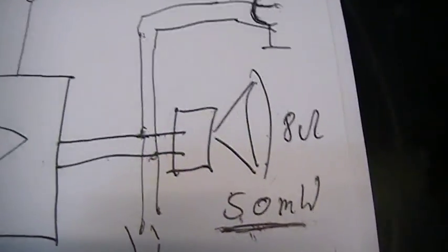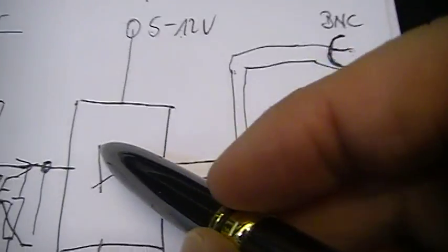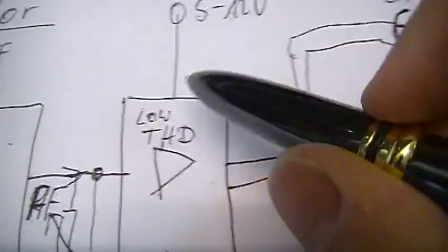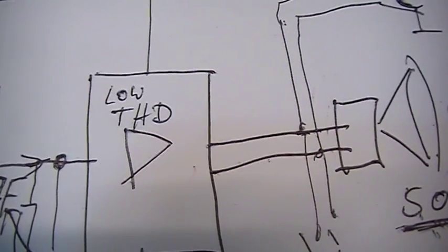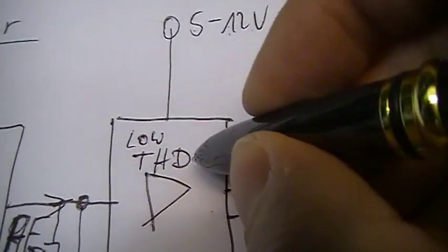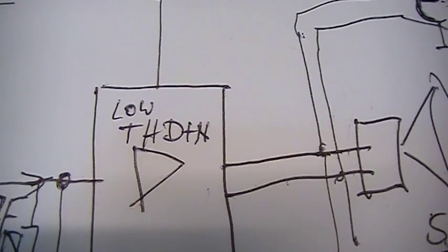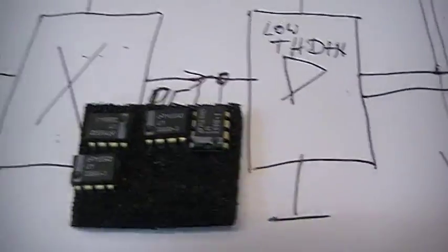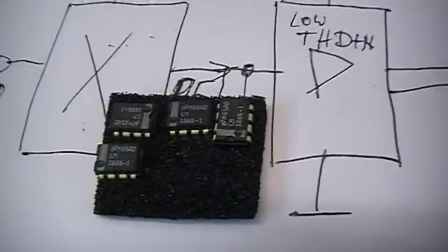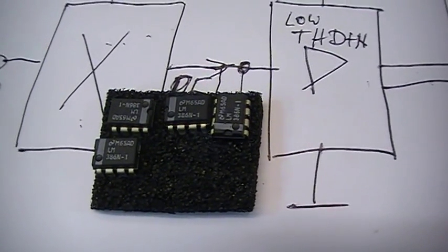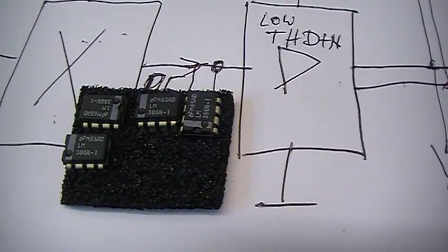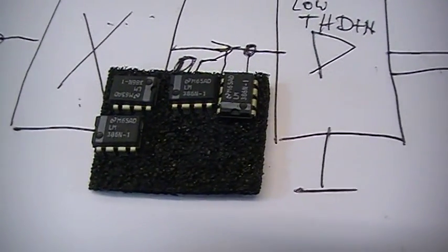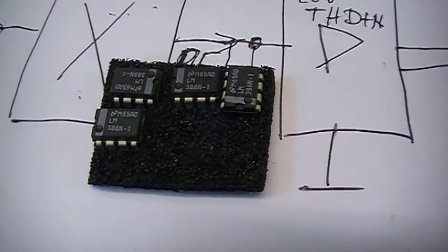So what we need as well is an audio amplifier with low THD. So that is a second requirement. THD is total harmonic distortion plus noise. That is how it is normally defined. And so, you know, the audio frequency stages in radios, in two-way radios, are somewhere between 5 and, in worst case, 10, something like that. I mean, 5 is not really bad.